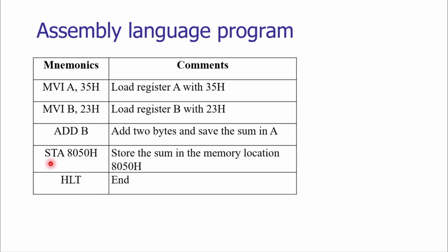Then we have to store. STA: the sum will be stored at 8050H. Whatever the sum of this operation is, it will be stored in the accumulator A, and that result will be transferred to the location 8050H. At the end, we are halting it. We are saying the program is completed. For that, the mnemonic is HLT, halt.